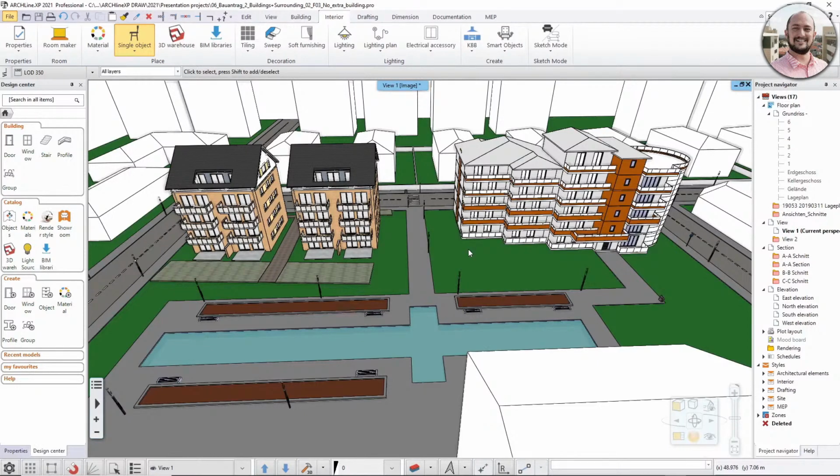After a short while, I can see that this reference has changed, updated with the latest changes. And then I can reflect those changes if I need to in my design, or I can just make something that connects the two buildings or something like that. So really, this is very useful when we're working together. Perhaps someone else is developing the park here in a separate file and so on. So we can link our drawings into each other's projects using several different formats and update that content.